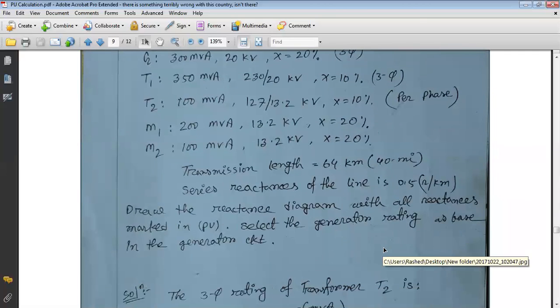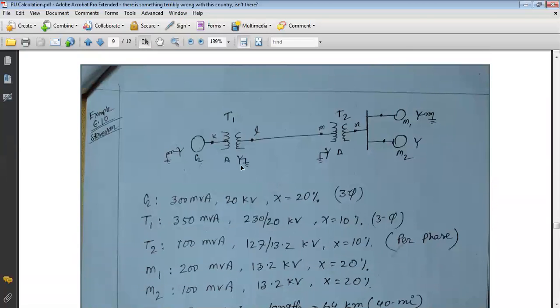So this is another thing: if we calculate the per unit reactance for the transformer considering the secondary portion or the primary portion, the result is the same. So per unit reactance is not affected by shifting the transformer side. It is unchanged whenever we calculate the per unit reactance. The reason is that for any portion, we consider the old and new rating for that particular portion, and the rating changes when moving between primary and secondary. So the base is shifted, and that's why the per unit reactance remains unaffected by the shifting of the transformer side.